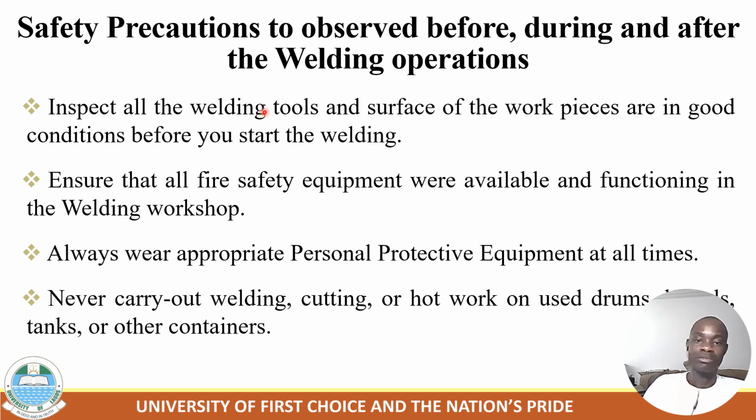Safety precautions to observe before, during, and after the welding operation. You have to inspect all your welding tools and equipment very well before, during, and after you finish the welding operation, and ensure that all fire safety equipment is available and functioning in the welding workshop in order to prevent or quench any accident that may erupt during welding exercises.